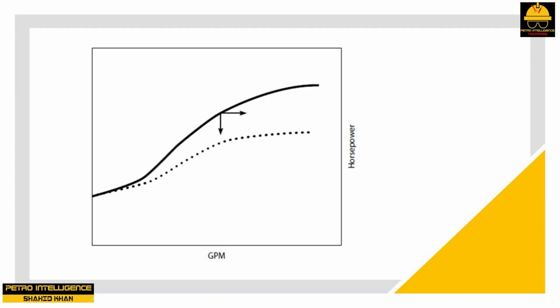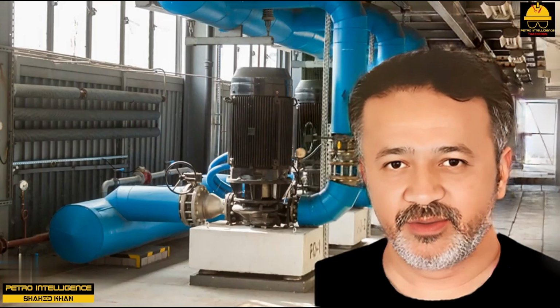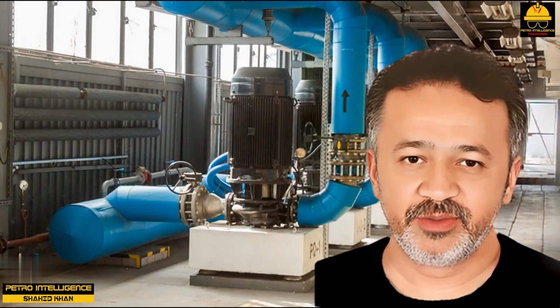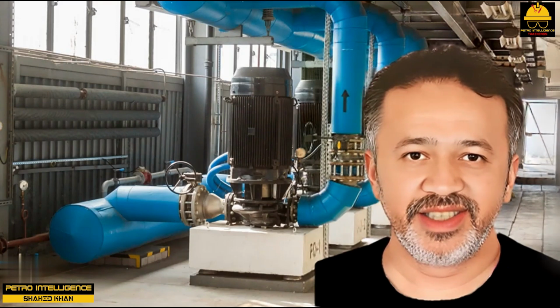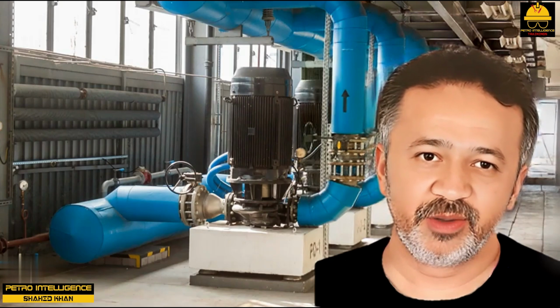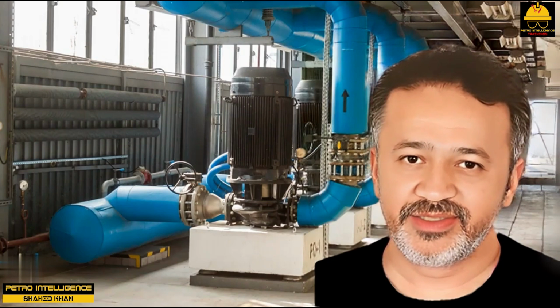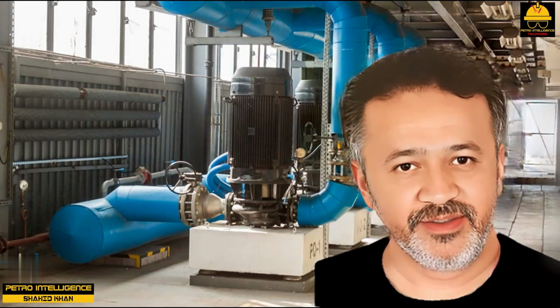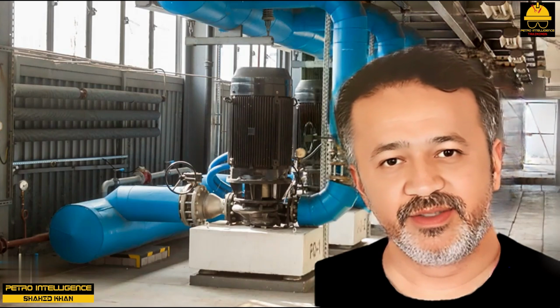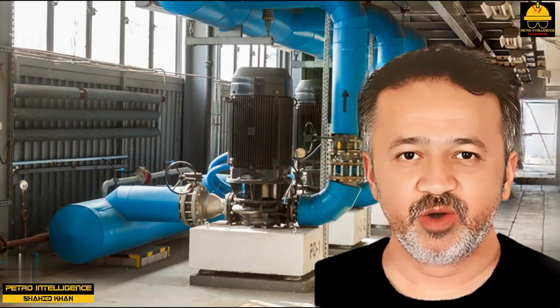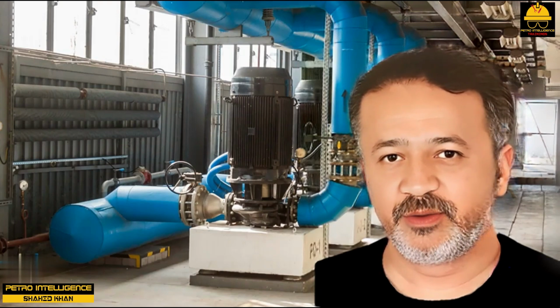On the steep part of the pump curve, the flow increases slowly, while the head drops off rapidly. Hence, the product of GPM times feet of head remains the same or goes down. The response of the amp load on the motor driver is an indication of pump performance. A pump operating on the proper, flat portion of its curve will pull more motor amps as flow increases. A pump operating on the poor, steep portion of its curve will not pull more amps. If the manufacturer's horsepower per flow curve indicates that more horsepower is required as flow is increased, but the motor amp load is not increasing, then something is wrong with the pump.